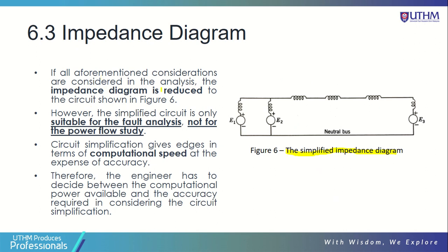The impedance diagram is reduced to the circuit shown in figure 6. However, the simplified circuit is only suitable for the fault analysis, not for the power flow. Circuit simplification gives an edge in terms of computational speed at the expense of accuracy.